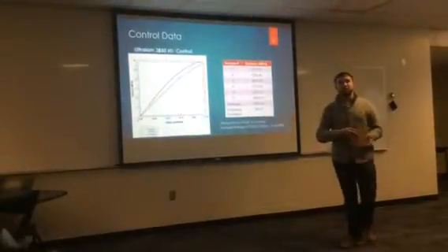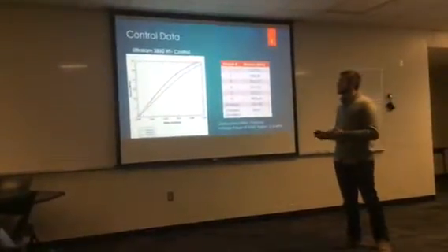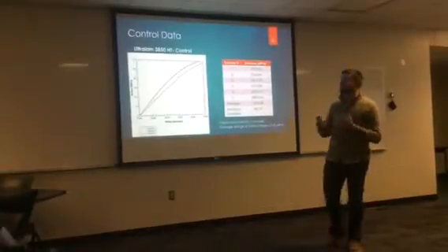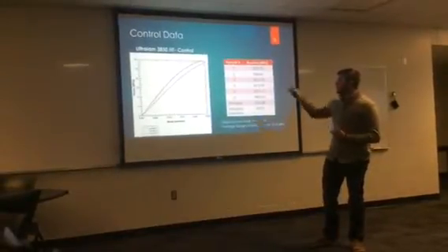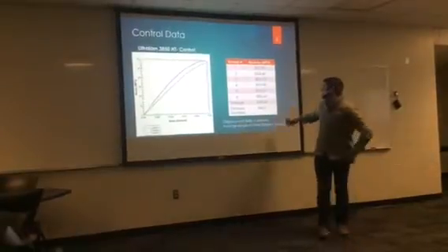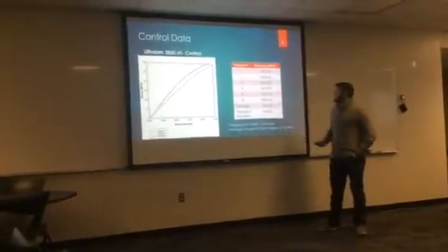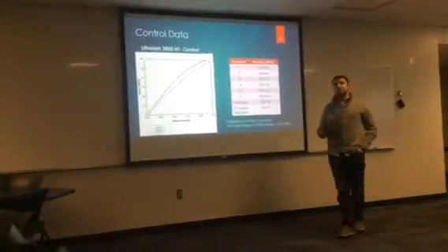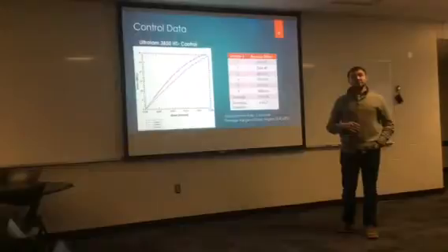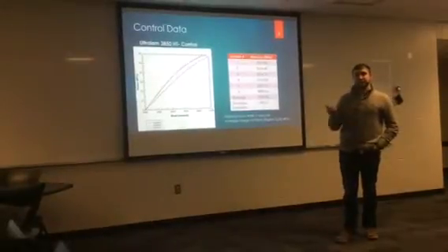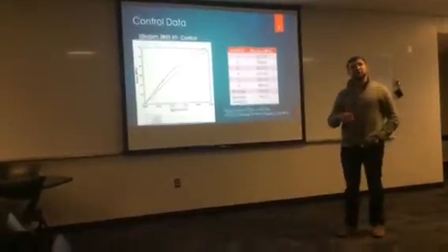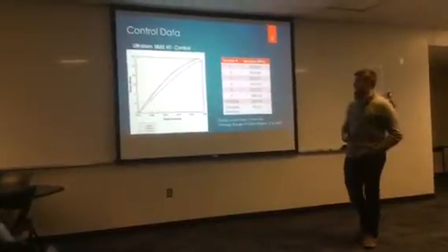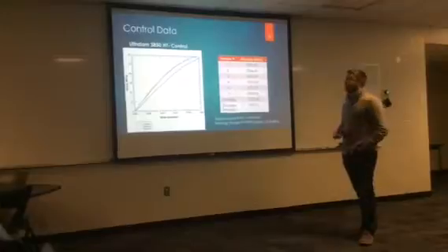So now I'm going to move into talking about my actual data and results. Before I could run any actual tests with my aged samples, I needed some control data. So here's a graph of my control samples. As you can see, I ran 6 samples that have an average modulus of 3,200 megapascals with a standard deviation of about 342. This is what is to be expected, as the reported modulus for ULTRALAM is about 3,200 megapascals with a range of about 240 megapascals. So this is consistent with what we would expect.